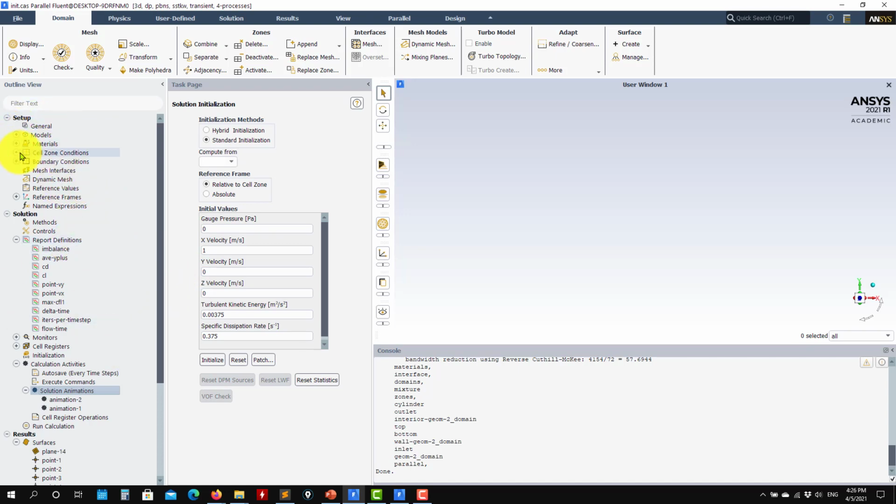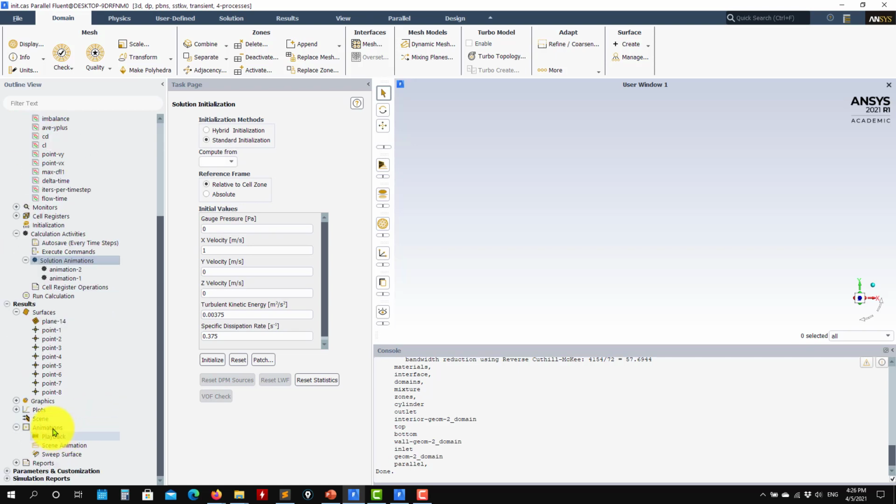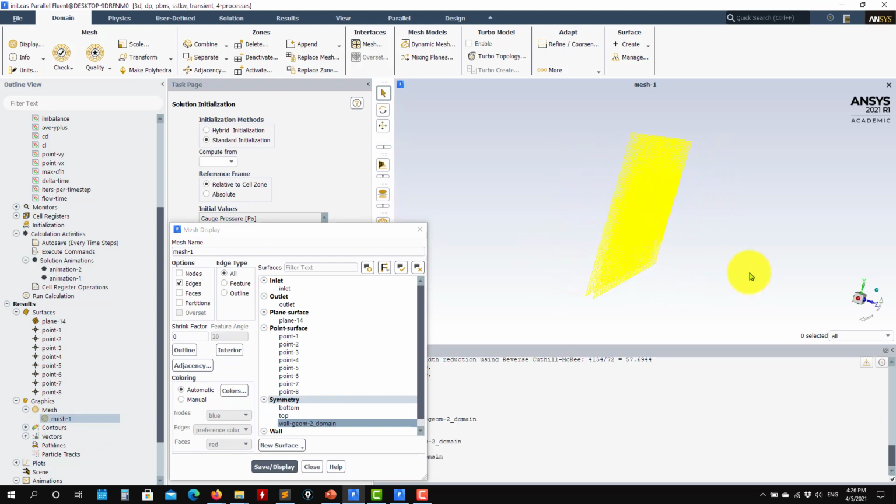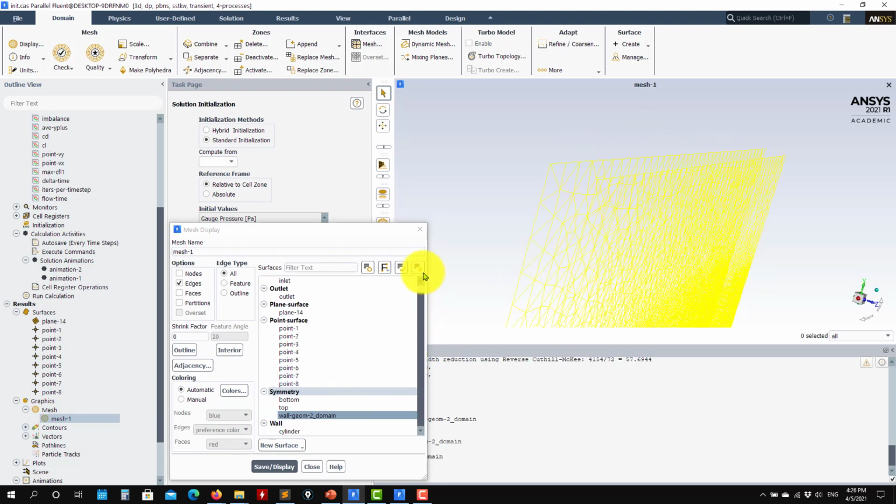This is reading the settings file. See that pretty much everything is the same. What is important, as I mentioned, is that when reading this mesh, let me plot it here, you see that it's a fully 3D mesh. You have these two faces here. In my case, I grouped these two faces in a single patch. It might be better to have front and back. Nothing changed, it's exactly the same. As you have this, you can also create a plane, and now you have the mid plane, and you can do all your post processing there.